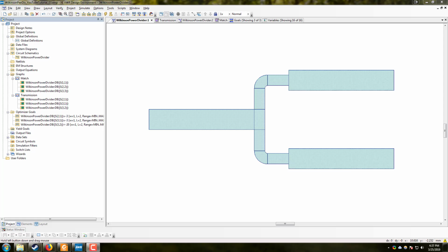A software like ANSYS HFSS is a three-dimensional full-wave EM modeler, and in that program you will get even better estimates on the performance of the component because you're taking all three dimensions into consideration. In a solver like what we'll be using here, you're basically slicing your component into 2D slices and you're solving those, and so as a result you're again introducing a little bit of error. However, this gives you a pretty solid guess at how your component is going to behave.